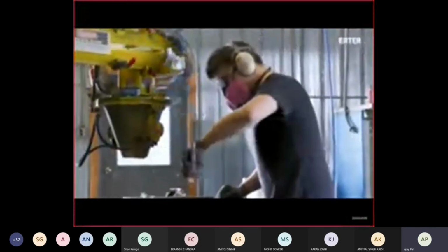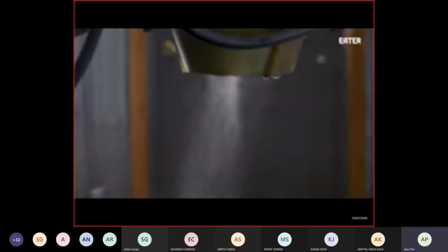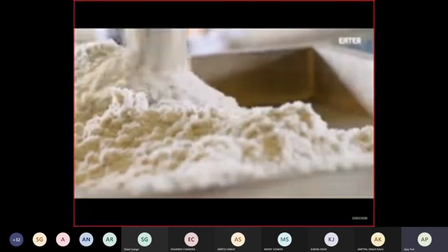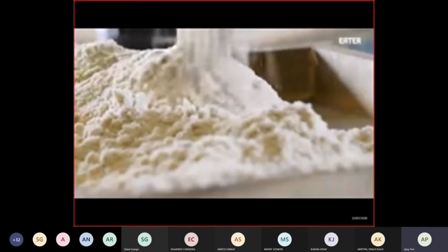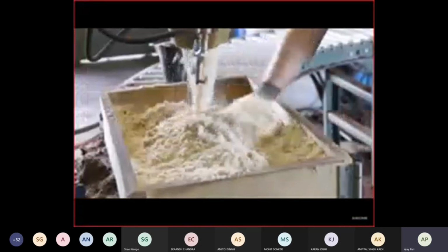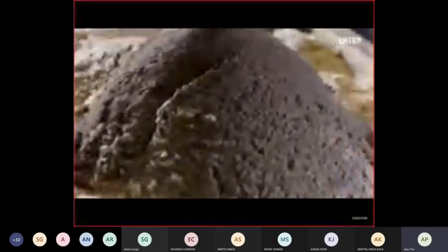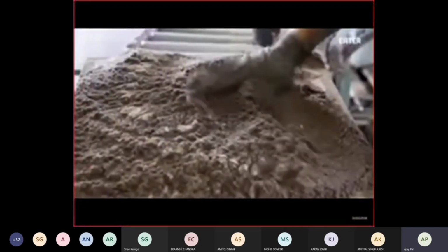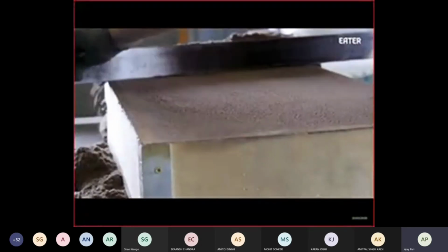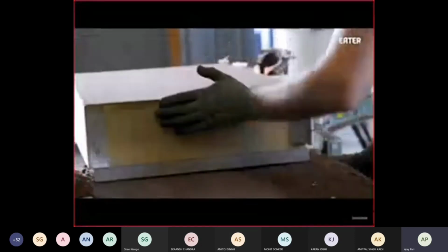With the mold making, it's just an attention to detail and a level of practice. We use a new sand for the very face of the mold, a mixture of sand with a little bit of resin binder in it to hold it together. New sand is really angular. All those angles mesh with each other and form a really smooth surface. But then the bulk of what we're putting in the mold is reclaimed sand. It takes practice to know how quickly to pack the sand together so that when you pull it off the mold, it doesn't leave all the letters and the logo behind and things like that.